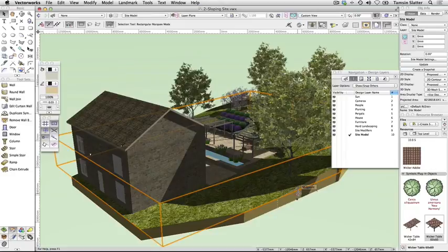Select the site model. Where earlier in the tutorial we created floor objects at different elevations to represent the site, here the entire site is represented by one single object that sits below all the design elements. The surface of this object changes as the levels of the site change. Let's examine the source data for the site model. Like the earlier simple slope, this example model was also created from a series of spot heights measured across the site and entered with the Vectorworks stake tool.